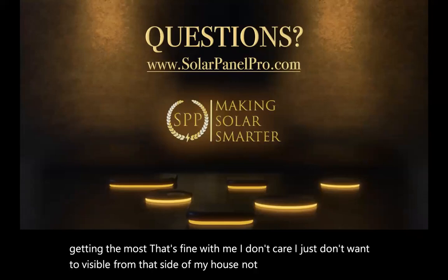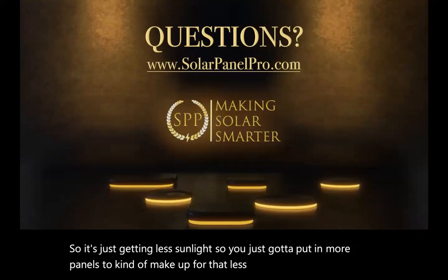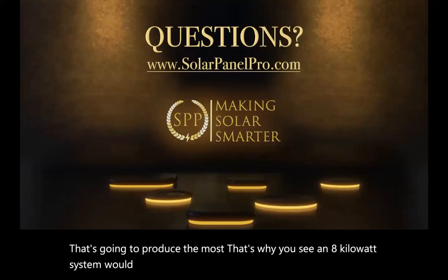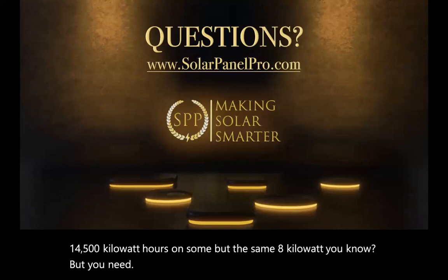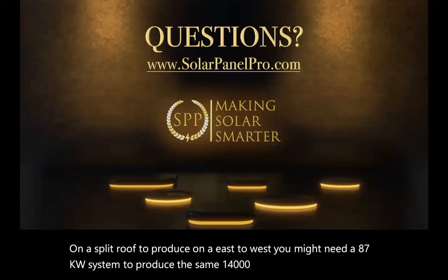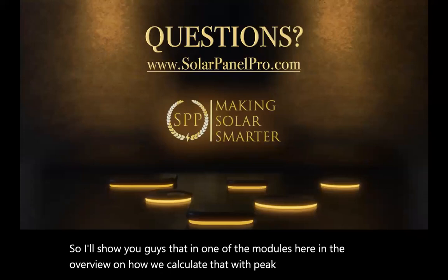Not a problem. So it's just getting less sunlight, so you just have to put in more panels to make up for that. Because direct sunlight is going to produce the most. That's why an 8 kilowatt system might produce 14,500 kilowatt hours on some roofs, but on a split east to west roof, you might need an 8.7 kilowatt system to produce the same 14,500 kilowatt hours because the sun factor changed. I'll show you guys that in one of the modules in the overview, on how we calculate that with peak sunlight hours and stuff like that.